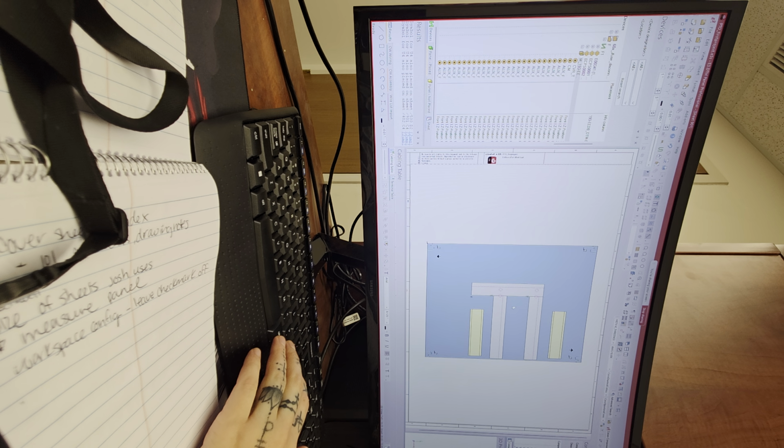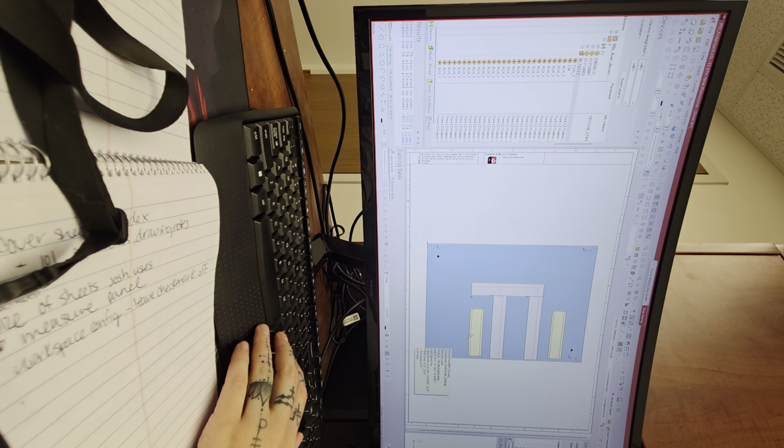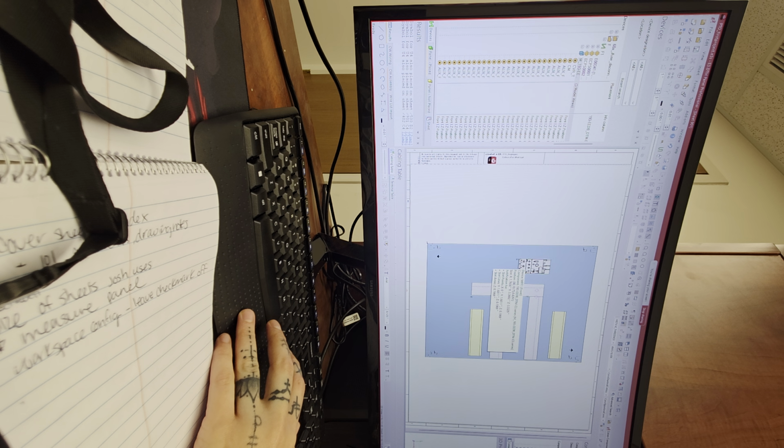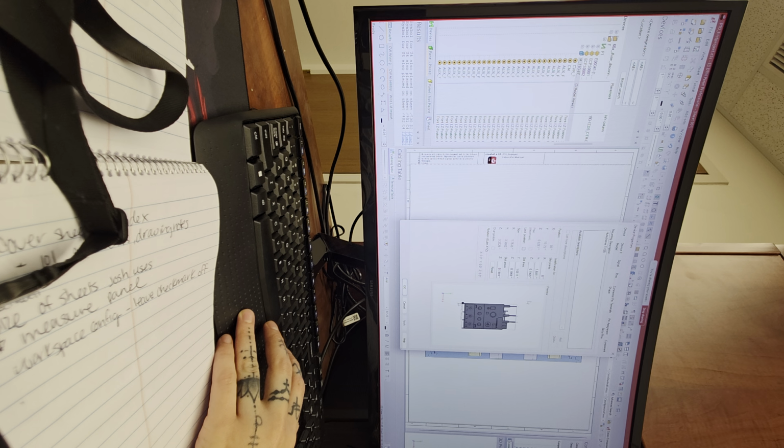All right, so let's just put that on your DIN rail itself. I think that's where it's supposed to go. Well, I'll put this on a mounting plate. Just first find out what the mounting description is for this. Does it even go on a DIN rail or not? Right click on this component. Let's click on device properties, and let's click on shape. That's usually where all these mounting descriptions are stored.